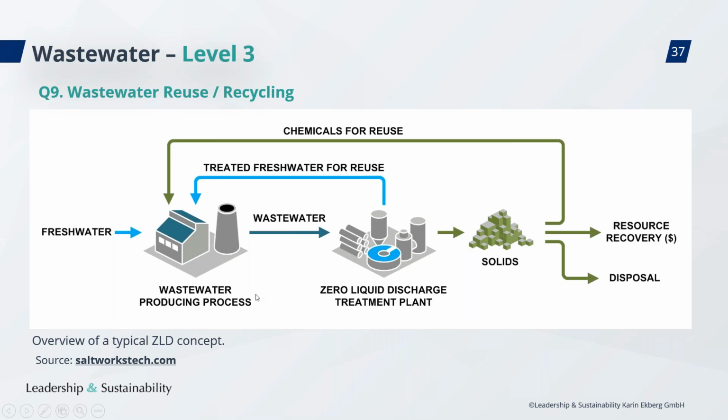So you have your wastewater, you have your factory here where you're producing your wastewater, and then you treat it in a normal treatment plant, and then you have your zero liquid discharge treatment plant, you have your solids and hopefully resource recovery or disposal, and then perhaps even chemicals that you can reuse and feed back into the plant. And in any case, you have this blue stream here with the treated fresh water for reuse.